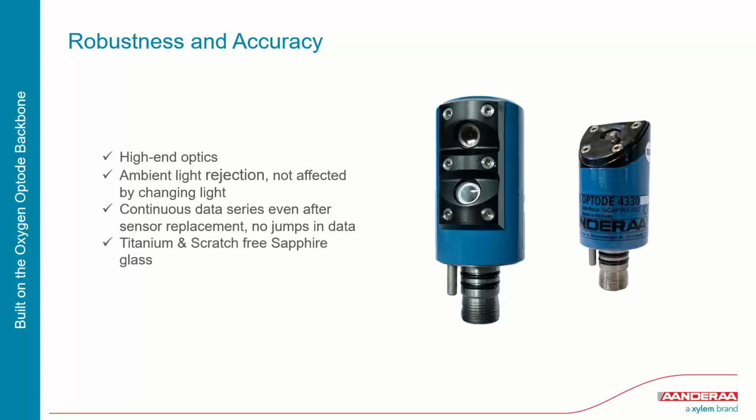And because of this calibration that we do with our sensor, if you replace the sensor with a new sensor when you're taking one in for maintenance or you're just changing things around, because it's calibrated completely, their measurements will correlate and will be the same.